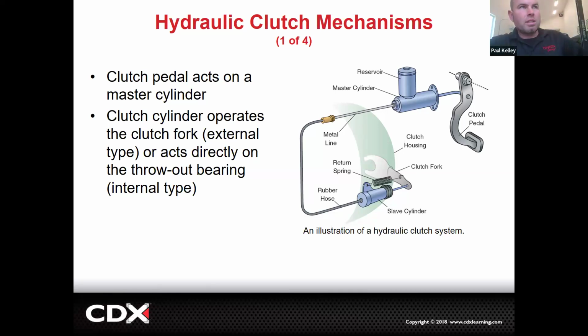That would just mean literally this push rod right here is adjusted too long. It pushes your pedal all the way up. That's why it's hard and high. But more importantly, it actually pushes the fluid. So the fluid's already pressed. Your clutch pedal's up, but your fluid's already pressed, which means the slave cylinder's throwing your fork and your fork's already starting to release the clutch, even though your clutch pedal's up. If your clutch pedal's up and you're racing, but your fork is already kind of pushing on the release and your clutch is partially released, it's going to slip. And that's it.